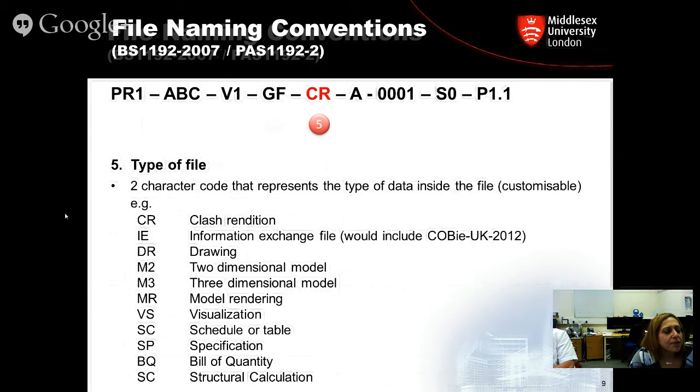Number 5, what type of file is it? What does it show? Is it an IFC file? Okay, so is it an information exchange file, i.e., is it a 3-dimensional file, an M3? Is it a visualization file, FS? Is it a bill of quantities, BQ? Is it a structural calculation, SC? Okay, so it's good to write what this model is, before you open it, what does it contain, all right? Who to direct it to? Are you directing it to the structural people? Are you directing it to the MEP people to continue on with the coordination, for the clash checking, avoidance and things like that?